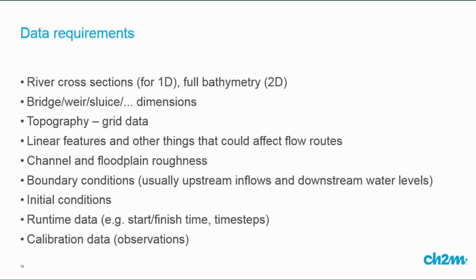The models now need boundary conditions, both 1D and 2D. Usually the upstream boundary conditions are inflows, that's flow against time if you're doing an unsteady model, and usually the downstream boundary conditions are water levels against time or rating curves generated from things like normal depth calculations.